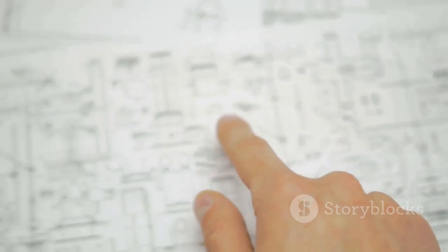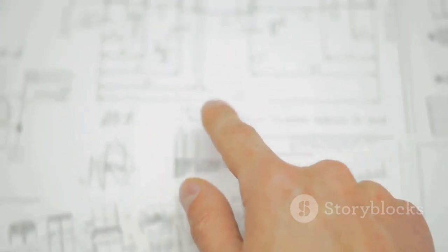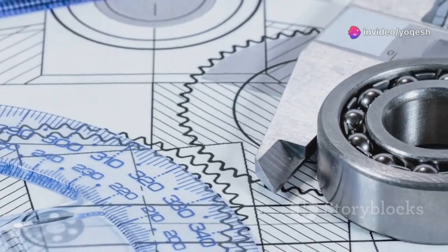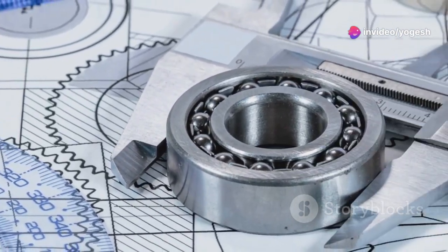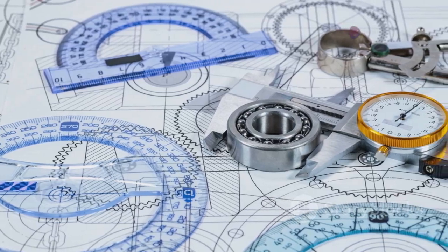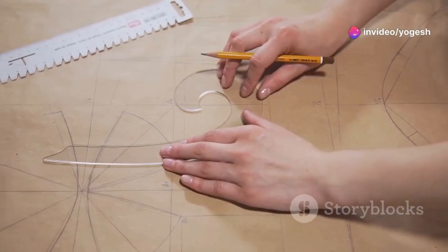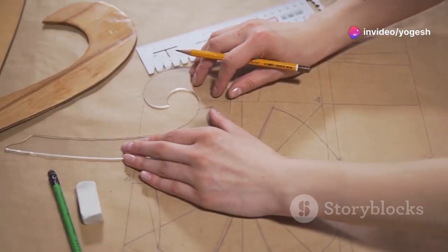Leader lines connect notes or call-outs to specific features. They're thin, angled lines with a short horizontal shoulder from the text. Avoid horizontal or vertical leaders. Use clear angles like 30 or 45 degrees. Never let leader lines cross or form a confusing fence. Neat, outward-pointing leaders keep your annotations professional and clear.